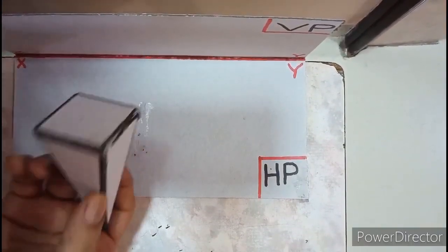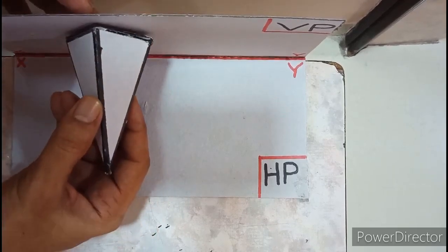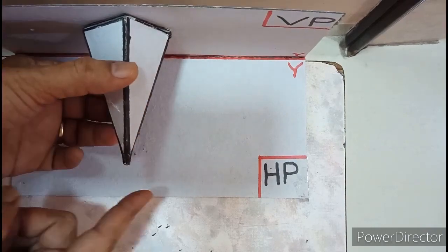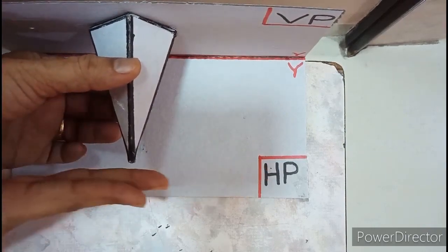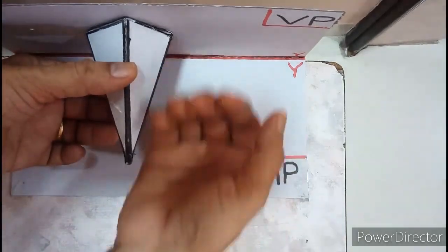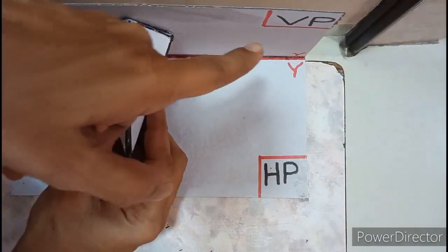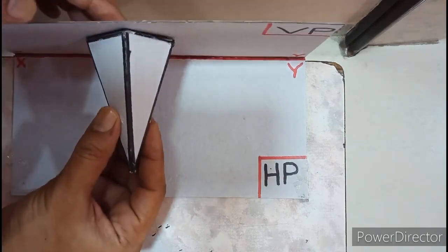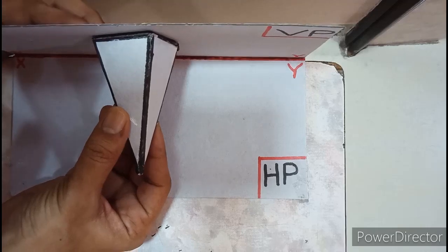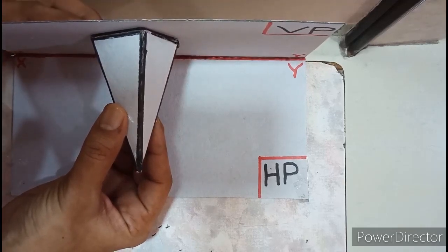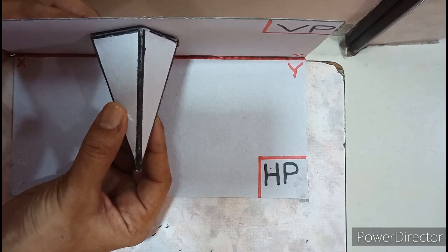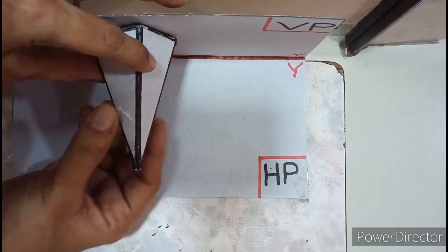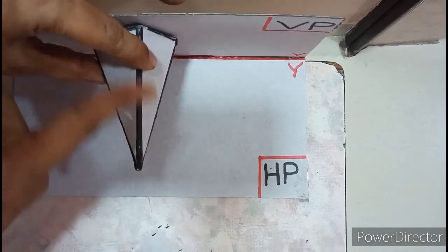So this was the first stage where the entire base was resting on VP, and on the right side you had a corner. In the first stage, if you extend this apex, it is 80 millimeter in front of VP. So this is the vertical plane, as you can read here. So the apex was 80 in front of VP. Now in the second stage, all of you remember that when you draw the second stage, you should carry forward the first stage condition along with you. So this right side corner should be on VP, and this apex should be 75 in front. Right now it is 80. How will you make it 75?